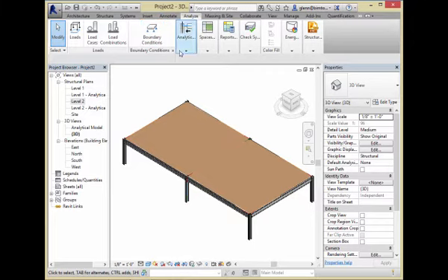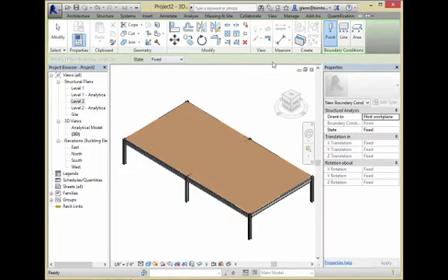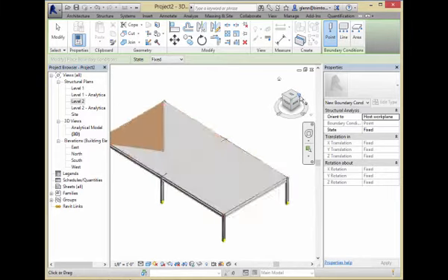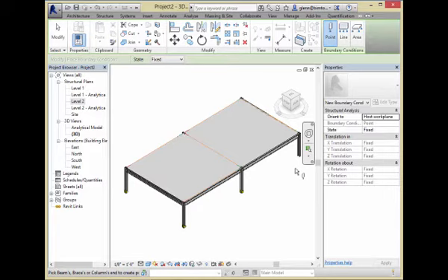If I want to add boundary conditions to my model, I'm going to put some at specific points. And I can put a little boundary condition under each of these. For the boundary conditions, you have the choice of, is it fixed? Is it pinned? You have all these different variations on it. I'm just putting these little boundary conditions. What I'm trying to do is put something there that's going to resist the load so that nothing moves in space. It's anchored to the ground and it can't go any further.